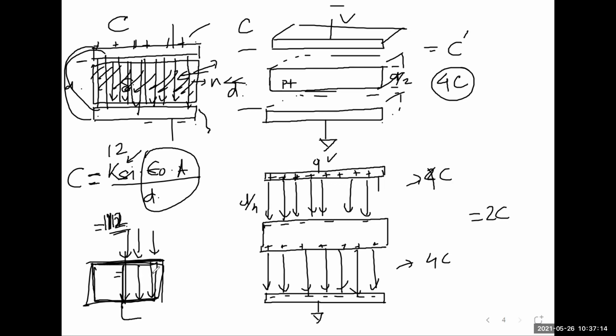Same thing with P plus, but in the case of silicon or silicon dioxide, you can have an electric field going through it because there is no conduction. There are no free carriers inside it, okay? So that's why in a P plus, what will happen is you get an electric field here, right? What is the majority carrier in P plus? Holes, right?